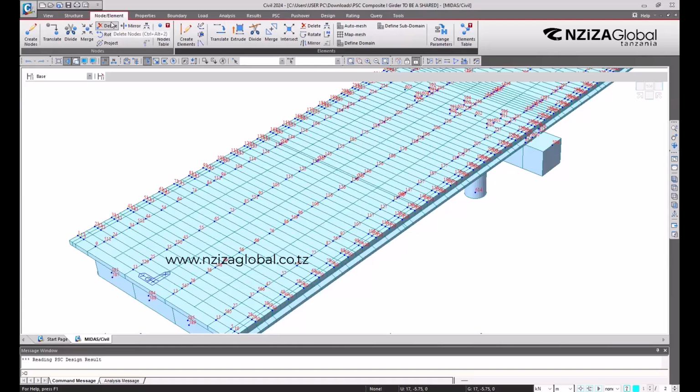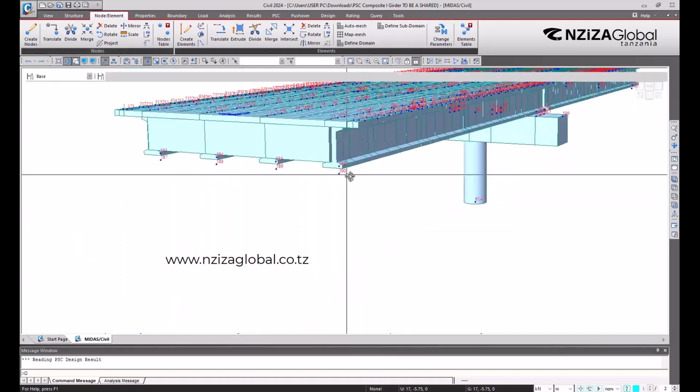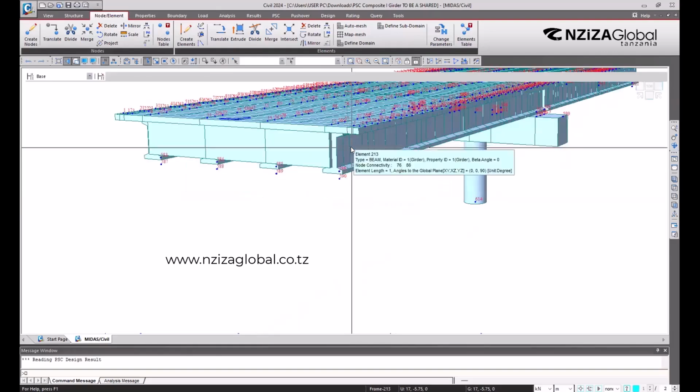But what the process is, you say the material properties, right? You create the material properties depending on which section you are going to use. Then you create the sections. We are going to see that later during the structure, or we will be modeling all the models that we use. I told you we will try to use the wizard, but for me, I'm not satisfied with it. You can use it, but you don't know really where they are coming from. But when you are using nodes and the elements, you really have your own touch. So we try to mix them.